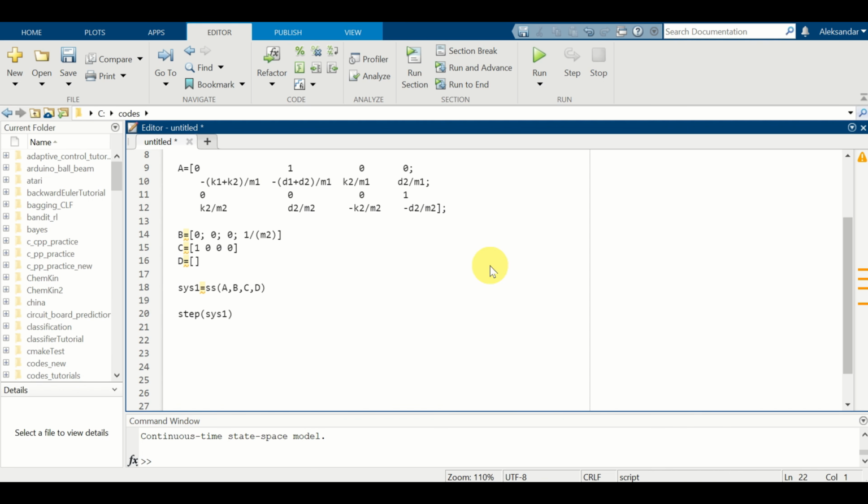First of all, let's define desired pole locations. Okay, so I will put them like this: pole location and desired. Let's call it like this. I will put one pole at -4, another pole at -6, and then I will have two imaginary poles. For example, -2 plus 2i and -2 minus 2i. We can see over here that all the poles are strictly in the left half of the complex plane. This means that our